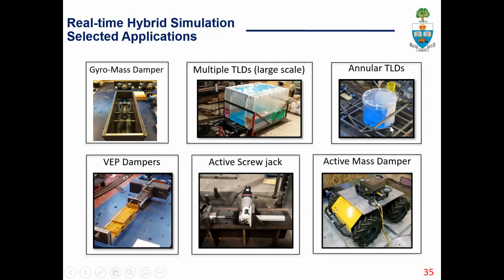The third device here is an annular tuned liquid damper, which is specifically designed for wind tower vibration control. And we have done real-time hybrid simulations to understand the effectiveness of this annular TLD in reducing the response of wind tower turbines.